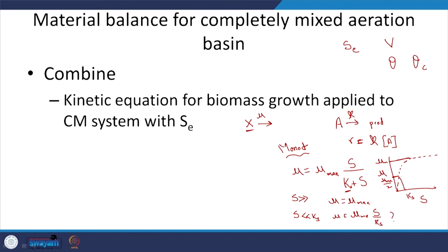So, here I need to know the rate of production of my microbes. So, that will be equal to, in similar terms, the specific growth rate into the concentration of the microbes, right. So, in the case where S is very high, you will have mu max into x, meaning the rate of production of the microbes is just dependent upon the concentration of the microbes, that is it.